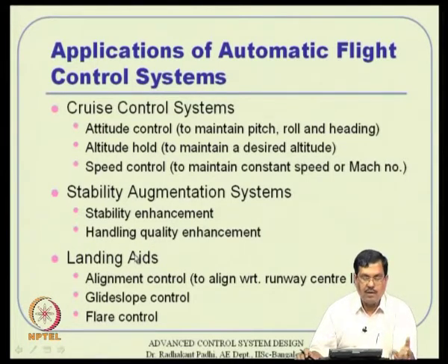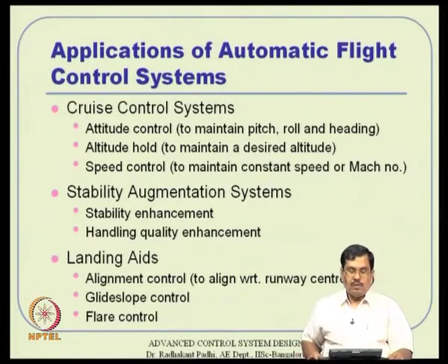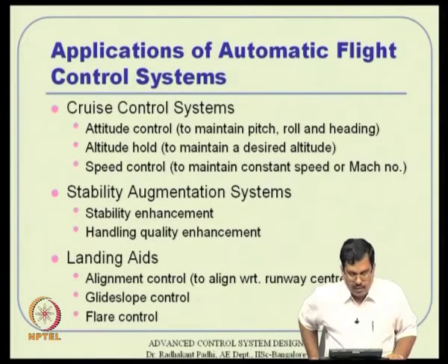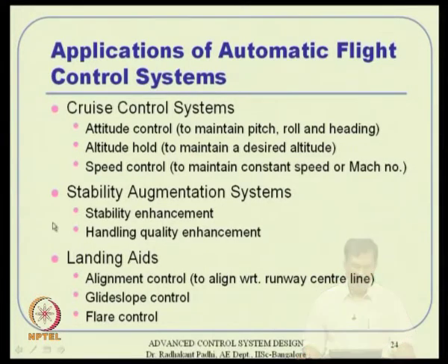How the pilot can handle the aircraft in a good way. In other words, he wants to give a command of, let us say, change the altitude from altitude 1 to 2, then the aircraft should really change it within that much time actually. And if he visualizes, let us say, let me pitch up the nose, the aircraft should pitch up and it should pitch up quickly, okay, without too much oscillation, too much overshooting, things like that actually. So, those qualities are called handling qualities, and stability enhancement and handling quality are roughly coupled with each other actually. Okay, that is one thing.